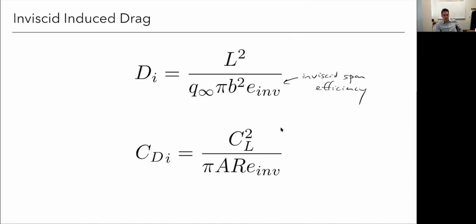Why do we call it induced drag? Well, the short answer is that the equations that govern this velocity field, we talked about these vortices, right, and their inducing velocity. Turns out it's exactly the same equations as the Biot-Savart law from physics. If you don't remember that, that's the physics that describes the magnetic field induced by an electric current in a wire. You got electric current, right? It induces this magnetic field. And I just said induces, right? And it's the exact same equations. So we say these vortices induce a velocity, and because it's that induced velocity that creates the drag, we call it an induced drag.